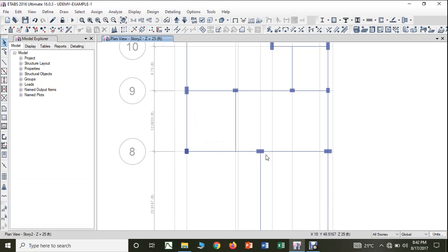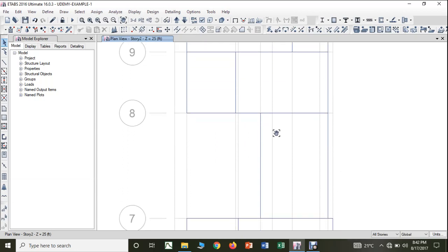Then what about this? This is proper because this is main beam, this is main beam, it is connected. Okay. And even if I rotate like this, then this area will be utility, so that will create eccentricity which is not good. So therefore let us keep the column like this only.